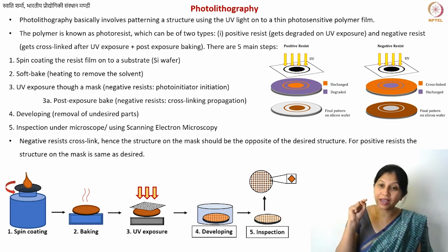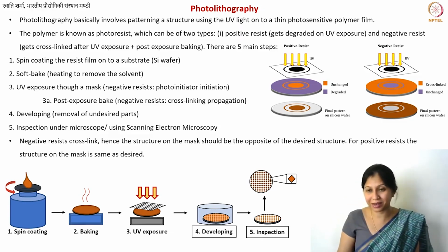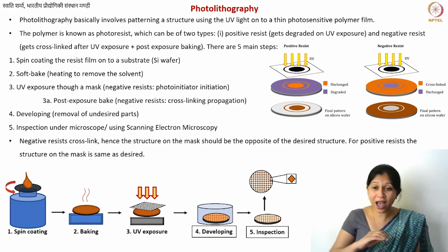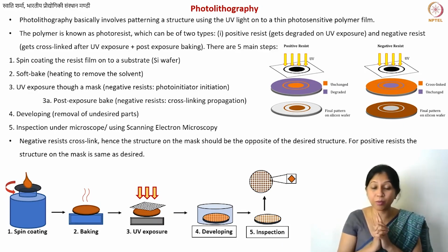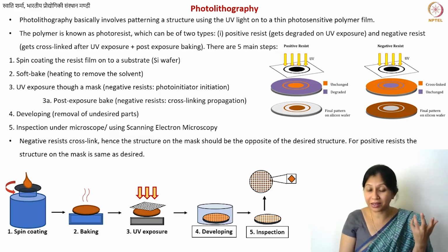They may not have the exact graphite-like hexagonal crystal structure, but they do have these graphitic sheets on top of each other. They may be randomly oriented. Random orientation is known as a turbostratic arrangement. So these are turbostratically arranged carbon structures that also contain some curved carbon structure. You can again think of the models that we had discussed. There is a coexistence of curved carbon structures along with these larger, turbostratically arranged carbon sheets.